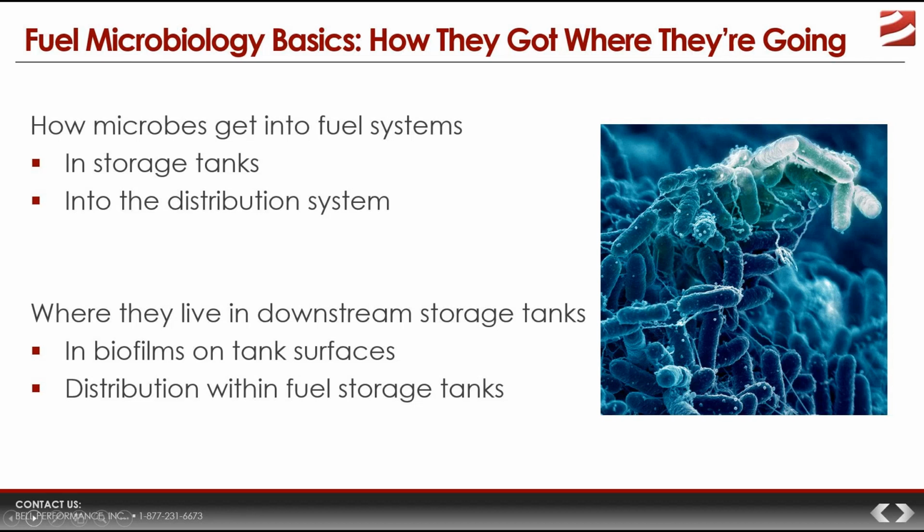Now, if you look into any storage tank, most storage tanks are going to have microbial presence. A lot of them are going to have biofilm, but that biofilm is not going to be evenly distributed. It's going to be concentrated in certain areas. And where it is concentrated, well, it depends on a number of factors, including what kinds of microbes are in there and what's already in the tank that best feeds what they need to grow.